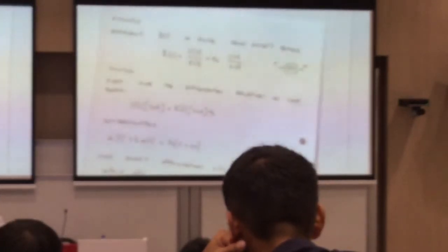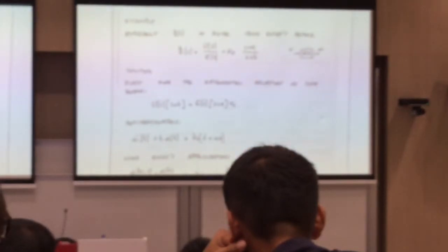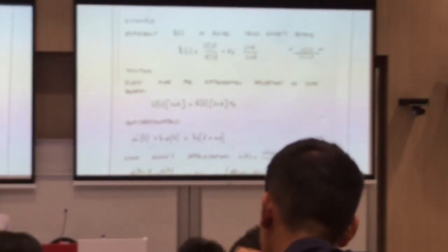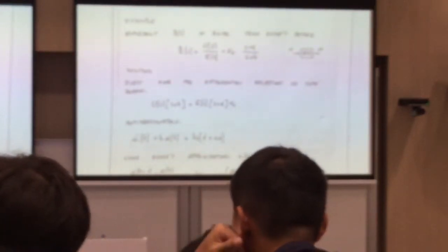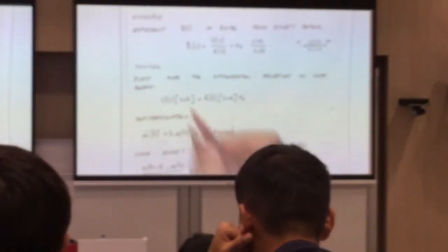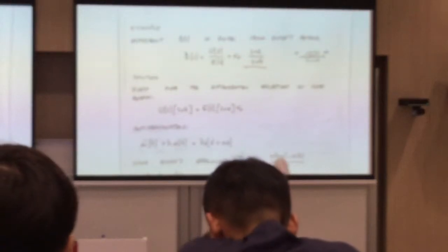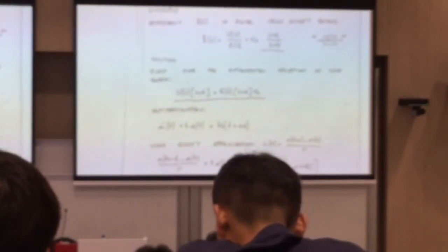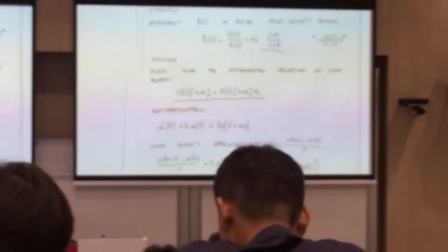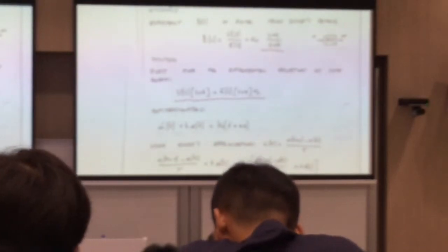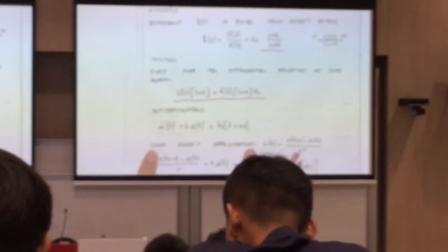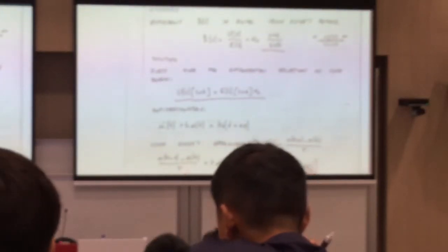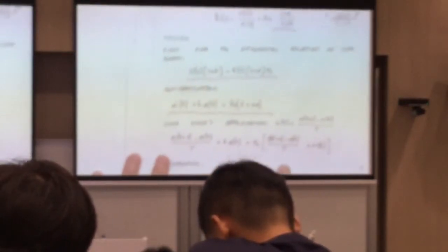So eventually you are able to get the difference equations. We have also done certain exercises on how to convert the analog controller to a digital one, presented by difference equations. The general process is, if you are given an S function, you need to expand the S function and take S as an operator. The S operator means differentiation. Then from your S function, you do the inverse Laplace transform to get your time domain, and then you get your differential equation. You may have first order, second order, third order. Once you get the differential equation, then you can apply the approximation.